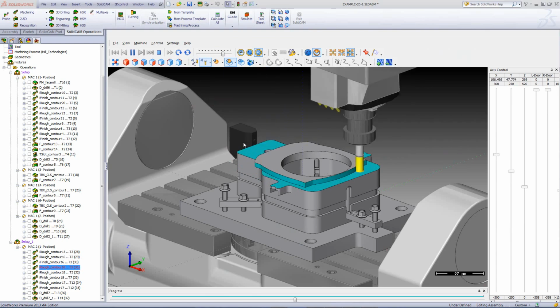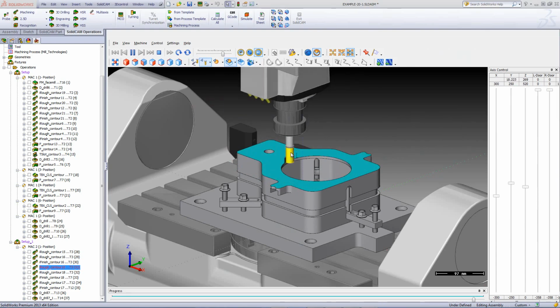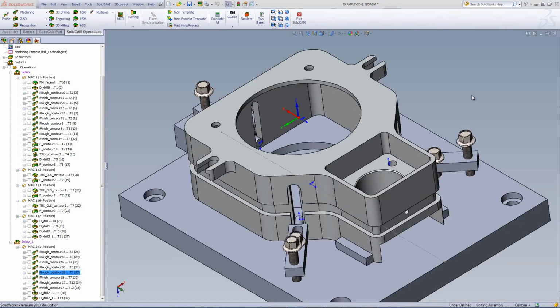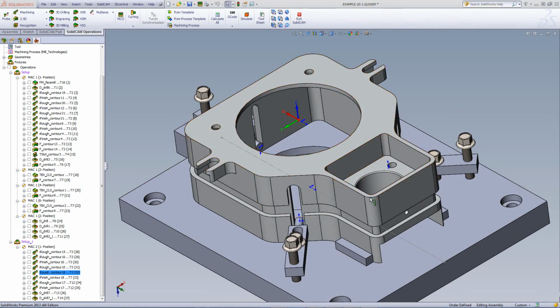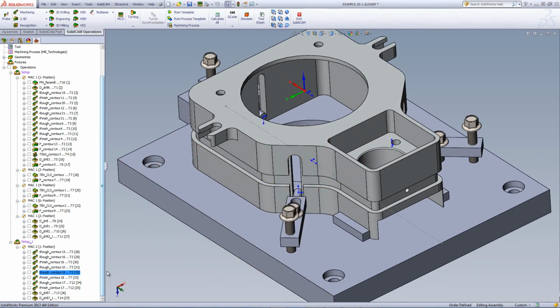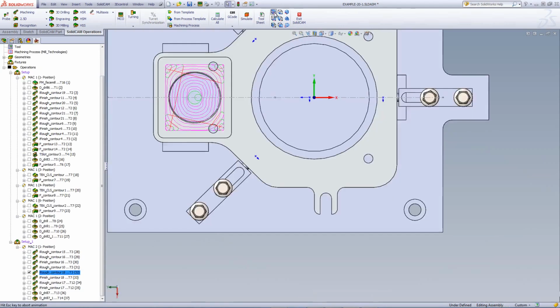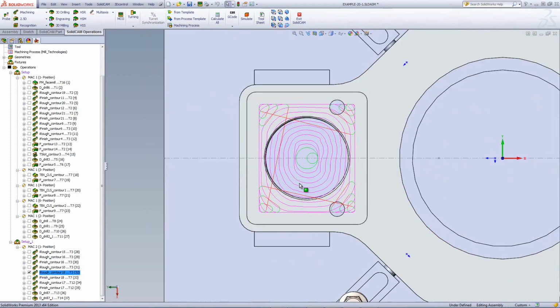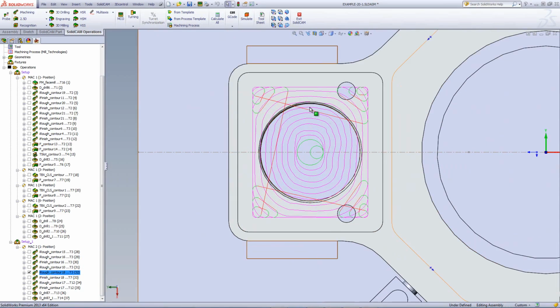And you can see that it works exactly around, cleaning up all of that material that was on that particular surface. Now, for my next operation, I still had to mill out this pocket over here. So again, just as before, I used the iMachining operation to mill out that pocket over there as well. Taking a look at the tool path from the top view, you can see that it has the morphed spiral tool path as well as trapezoidal for the corners itself.